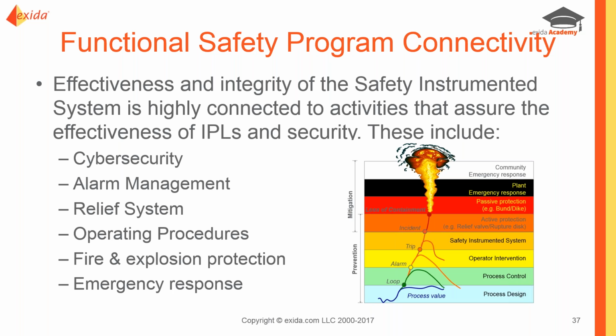Now, moving a little more into the details of documents, our functional safety management program is going to touch onto other parts of the process that are not necessarily part of the safety life cycle, but certainly influence it. And our independent protection layers that we credit in our risk assessment is a place to look for that connectivity.